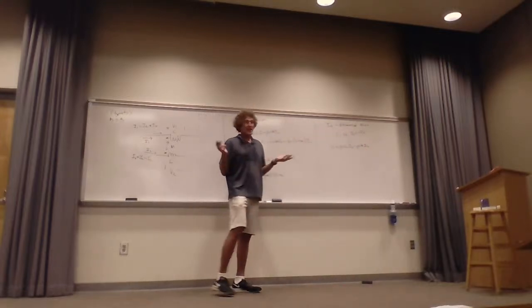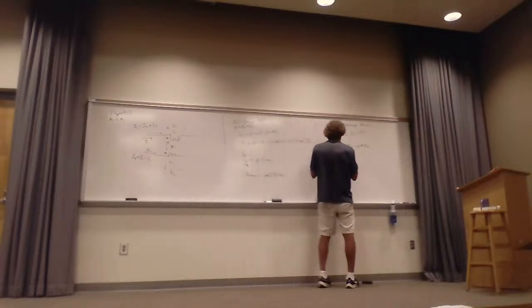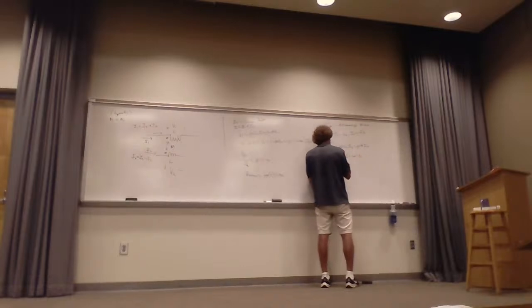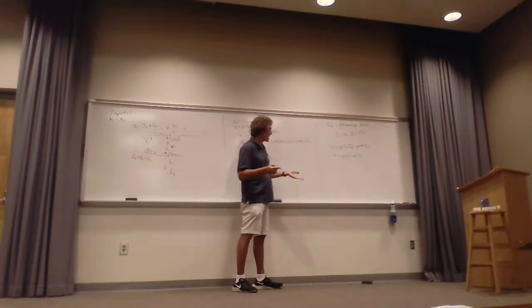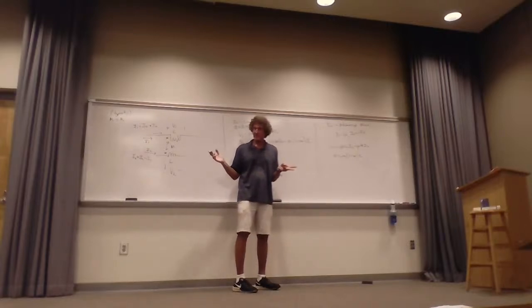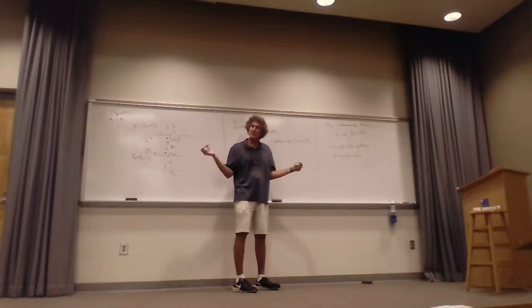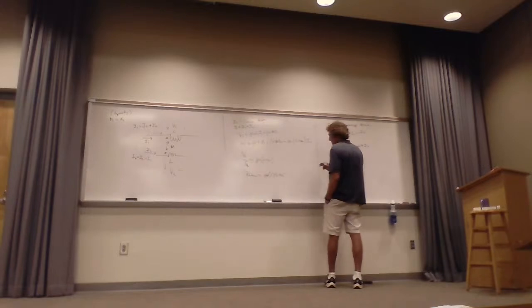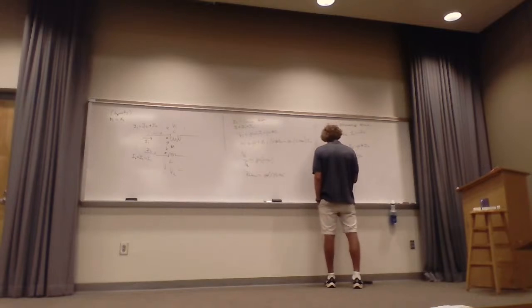Now I factor out ID. I don't care about the magnitude, but now I take a look at that and I get j omega times L minus M, times ID, is equal to V1. And if I look at the impedance of this, V1 over ID, it's j omega times L minus M, not plus. Y'all see that? And if L is just about M, it's about 0. Y'all see that? So it doesn't stop differential mode. That's very important. And if you take a look at the total impedance, call it Z differential.